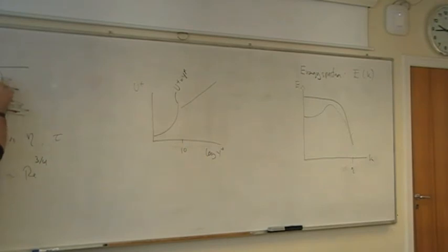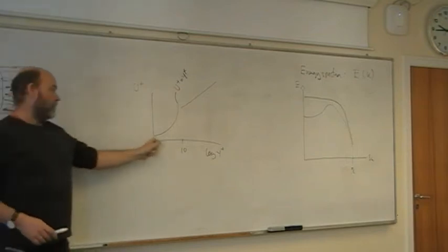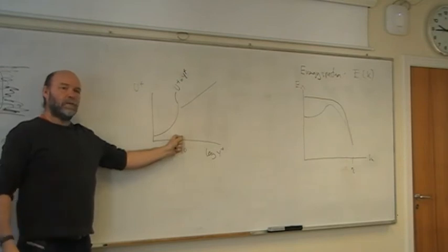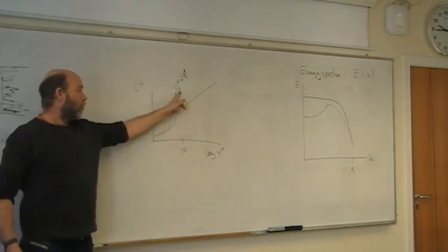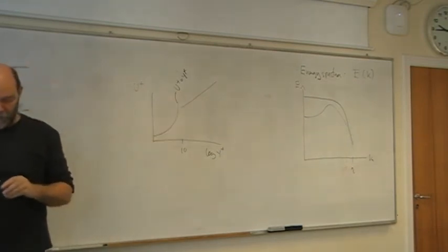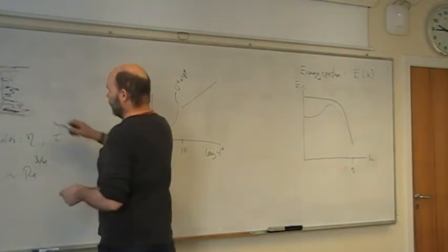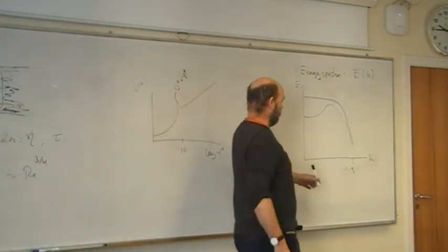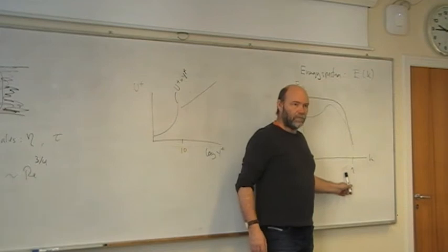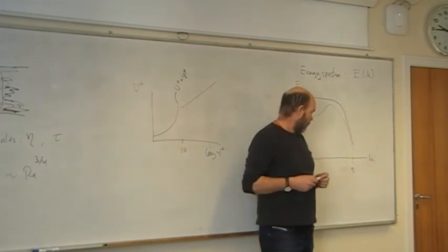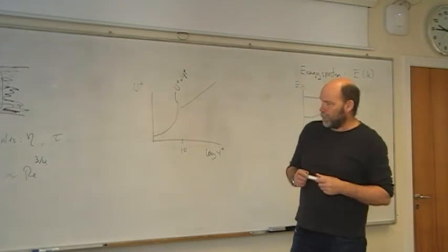So the average velocity, okay, fair enough, it will be laminar-like, but the actual activity, it's really here all the activity takes place. You really have to resolve this layer, although on average it will be like a laminar velocity profile, strangely enough. So you have to resolve the walls. But then further out in the free stream, definitely you can have bigger cells. So there you can cheat. 10 Kolmogorov should be a good approach.